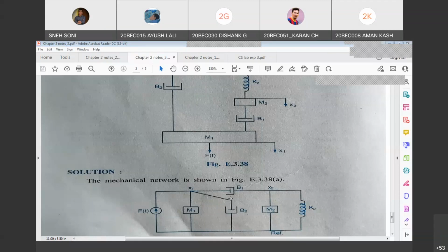Right. So how do we write the differential equations? Simple. Two differential equations will come here because there are two displacements x1 and x2. Okay. So when we write the equation of x1 or mass m1: m1 x1 double dot plus b2 x1 dot plus b1 (x1 dot minus x2 dot) equals f of t. This is my first equation. I hope all of you agree with me. Okay. In the second equation: m2 x2 double dot plus k2 x2 plus b1 (x2 dot minus x1 dot) equals 0. I think you are clear with the second equation as well.